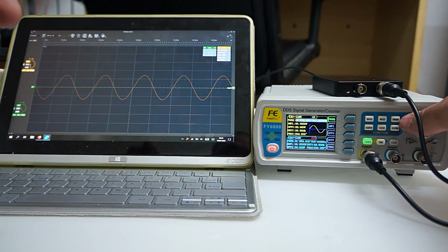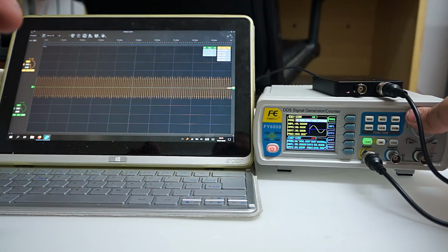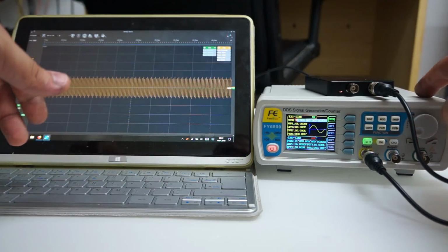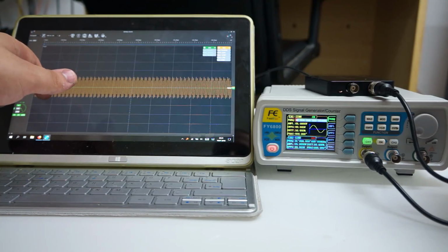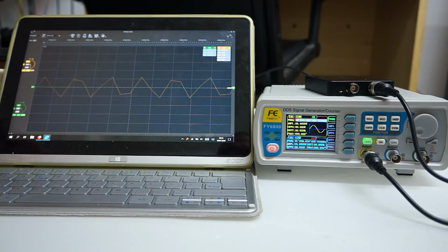I go to the most left digit, set it to 3. All digits turn to 0 except the one I just turned to 3, because that's my maximum. And the oscilloscope is displaying garbage because, well, 100 megasamples at 30 megahertz, that's 4 samples per half wave.